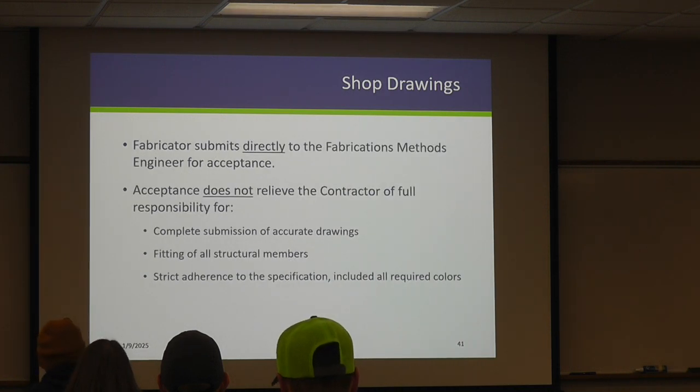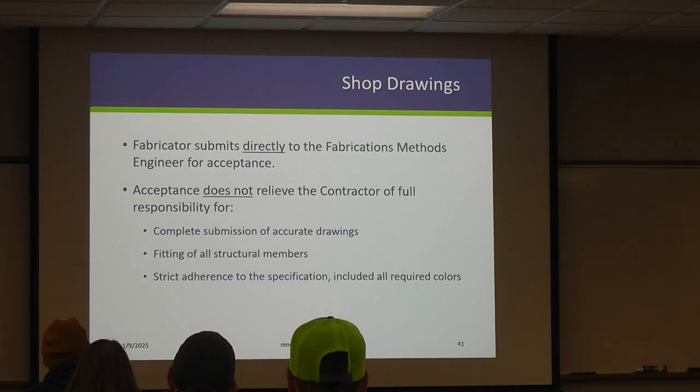So the fabricator is supposed to submit the shop drawings directly to the fabrication methods engineer. This oftentimes creates confusion, but the idea is the fabricator is really working back and forth with the engineer to resolve issues right away. And this is all happening outside of the project site. So shop drawings should be submitted directly.